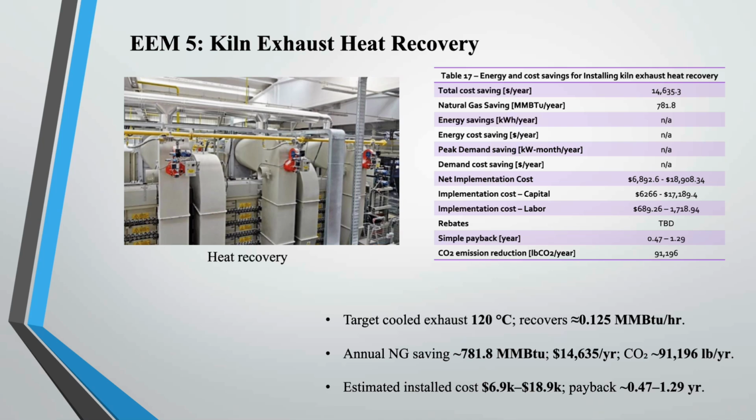So for the impact, this measure saves approximately $15,000 per year in natural gas cost. It reduces the CO2 emission by over 91,000 pounds annually. For the investment, the estimated cost is between $7,000 and $19,000. Because the savings are so high, the simple payback period is excellent. It's between 0.5 and 1.3 years.